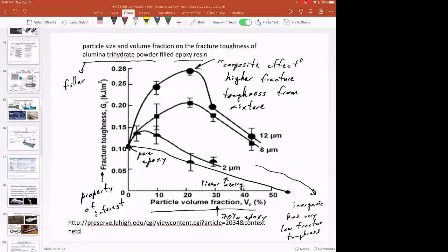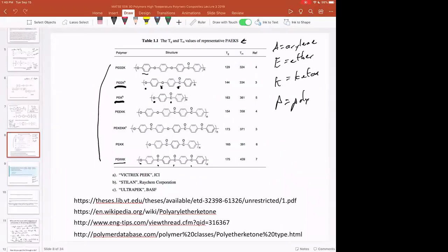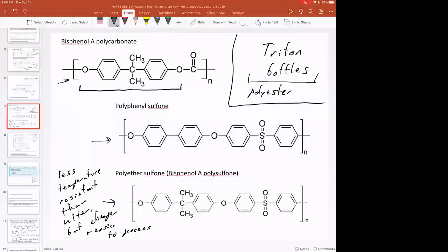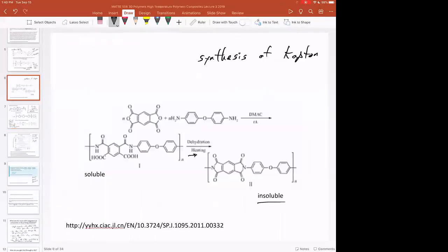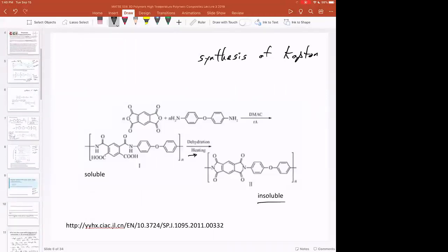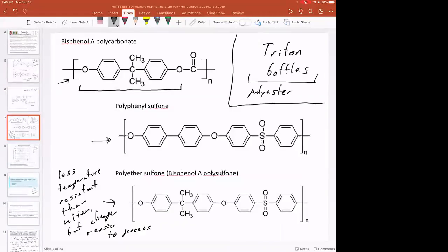Okay, so when we were talking about the PEEK family, which is right on this slide right here, and all the associated PEEKs. So PEEKs in general are semi-crystalline. So they have both a Tg, and any polymer that has a published Tm is automatically going to be semi-crystalline. But in some cases, like with this polyphenylsulfone, this one is amorphous, so it will only have a Tg. So you can look up all the properties of polyphenylsulfone, and you'll only see Tg. Same thing for polyethersulfone or polycarbonate, which we also talked about, which is on, I can't remember where polycarbonate is, but, oh, yeah, right here. Polycarbonate, polysulfone, and polyethersulfone. These will all be amorphous.